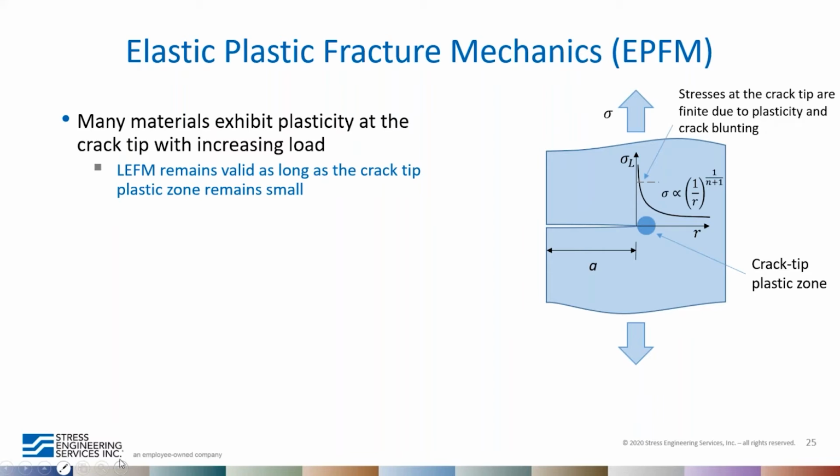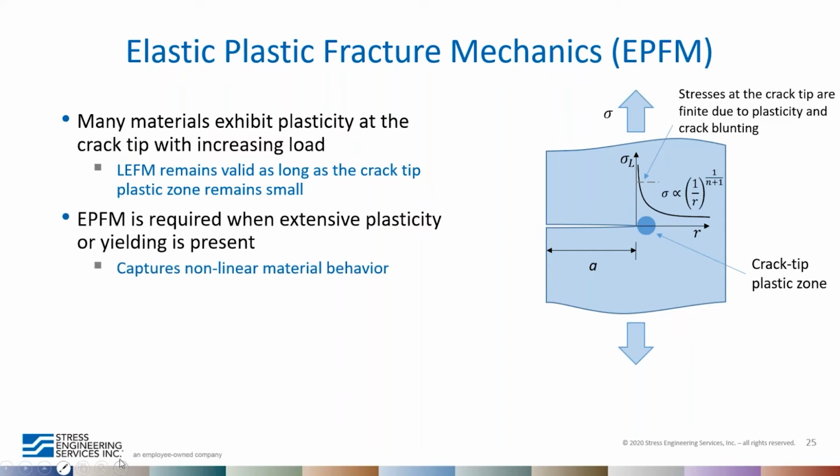Another thing to mention is that the stresses at the crack tip are actually finite. They're not quite infinite. Due to plasticity and blunting right at the crack tip, these stresses are finite. So when extensive plasticity is present, EPFM, or elastic plastic fracture mechanics, is required because it has the ability to capture both the linear and the nonlinear behavior.